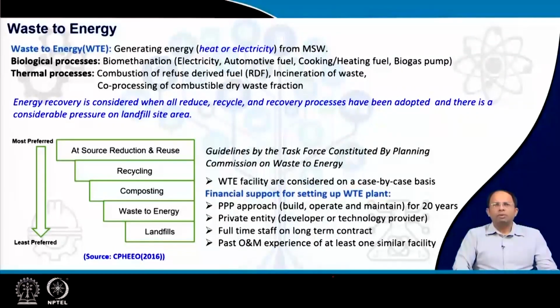So, we have already learnt about waste to energy in previous lectures. Waste to energy refers to generation of energy, either heat or electricity, from municipal solid waste, and usually this could be done via both biological as well as thermal processes. Biological processes include biomethanation. Again, we have learnt the basics about biomethanation earlier. Through biomethanation, we can produce electricity, automotive fuel, cooking or heating fuel, or we can run biogas pumps.